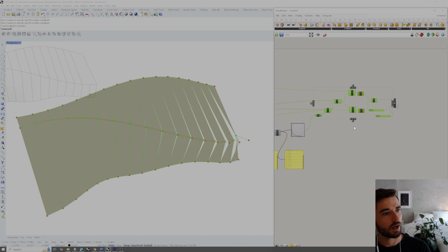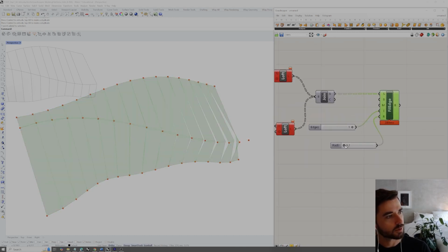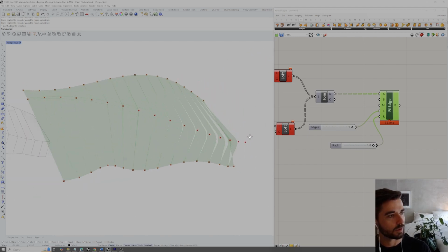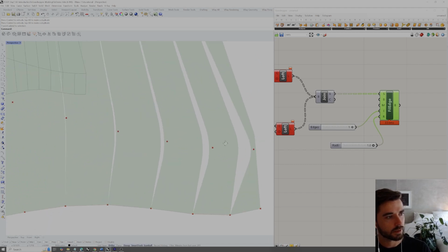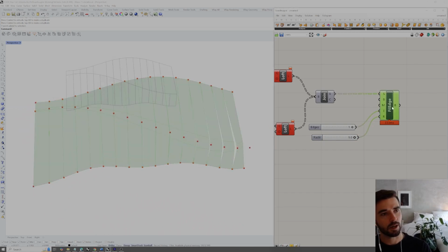And we can hide the preview of everything prior to this so it's a little bit clearer. And as we increase or scroll up the radius, we can see that larger radius is being applied to the geometry. So we're getting that nice clean radius applied to these fins. Now, we could just leave it at this, and we could bake this set.